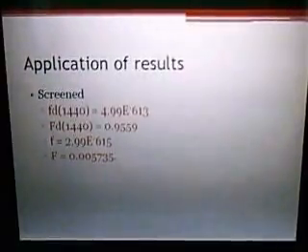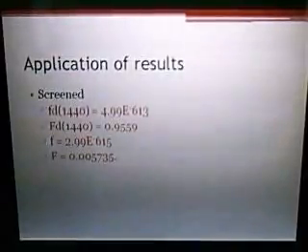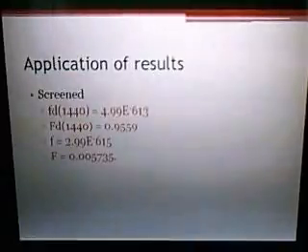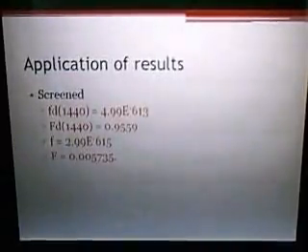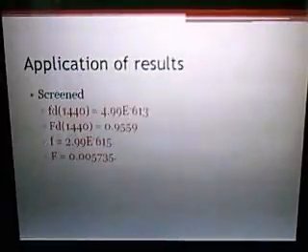So what our analysis is leading us to is that a burn-in screen is not really doable here. Not due to cost or equipment roadblocks, but rather a time frame, because the nature of the failure is prohibiting us from truly screening out all of the failures in a time-efficient manner.